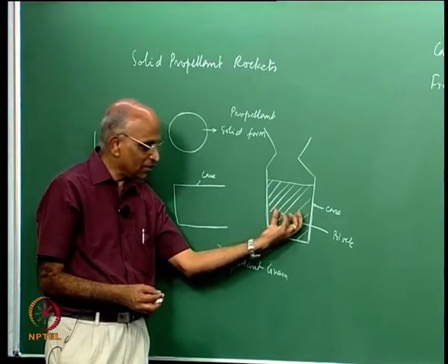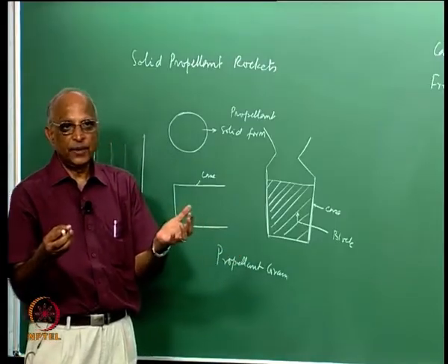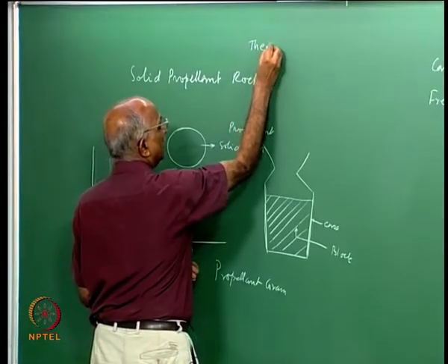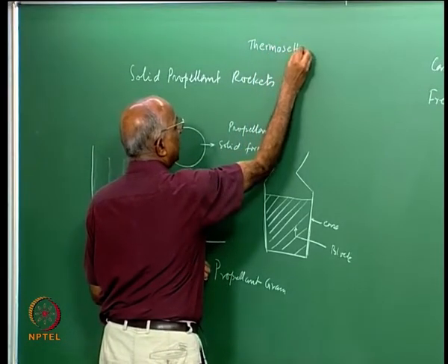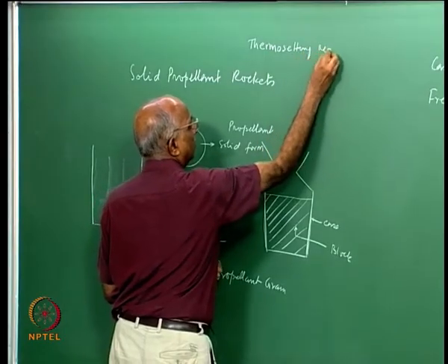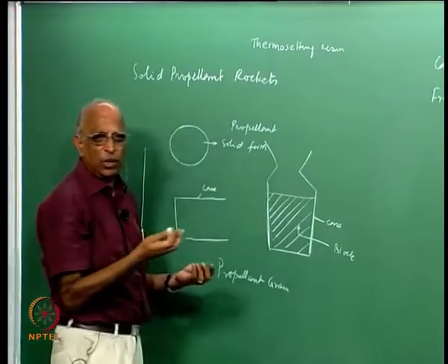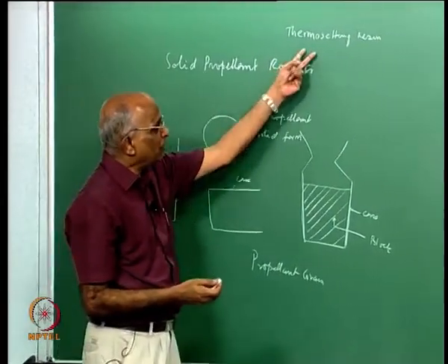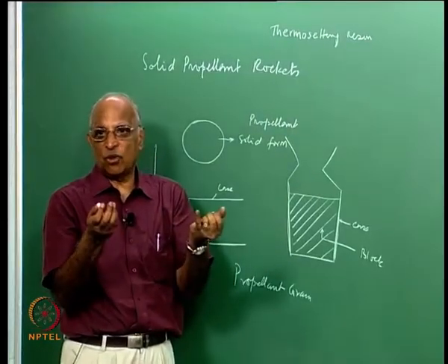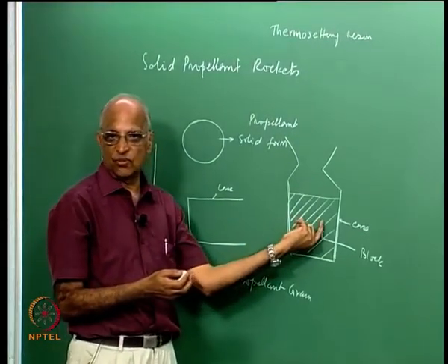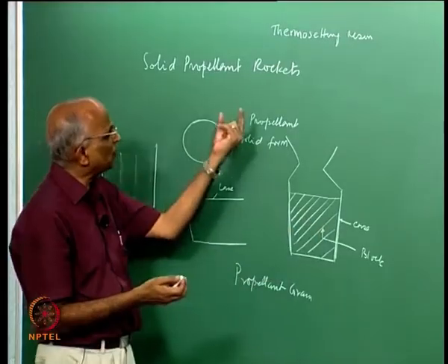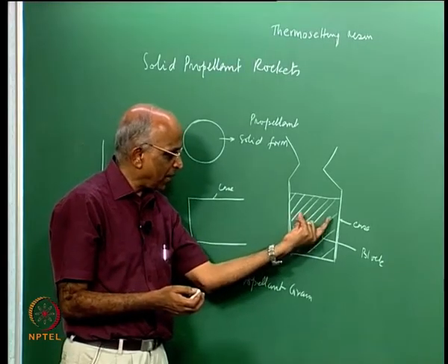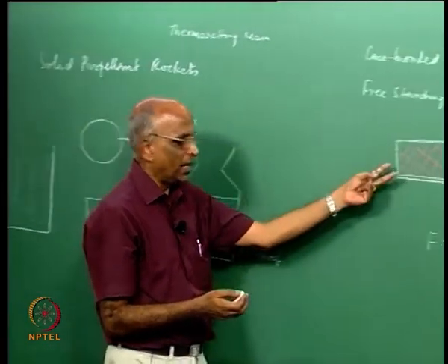This resin, when heated, sets, and is known as a thermosetting resin, because when heated it becomes hard. Resin is nothing but a polymer, polybutadiene, like glue. If you have plastic, which is also a resin, when I heat it, it softens. Therefore, we cannot use such resins for composite propellants. The same is true when I use nitrocellulose and nitroglycerin: I make it a liquid, I cure it, I make it a block, and this block is known as a propellant grain.